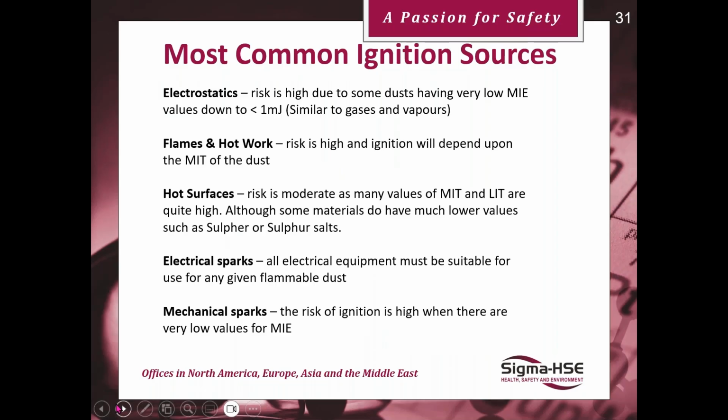Electrical sparks. All electrical equipment must be suitable for use in any given flammable atmosphere. This should be a given. And really, when you look at hazardous area classification, it started off life as electrical equipment hazardous area classification. So you can see how far back it goes. So hopefully, when you look at your electrical equipment, you can make sure it's safe for use within zoned areas.